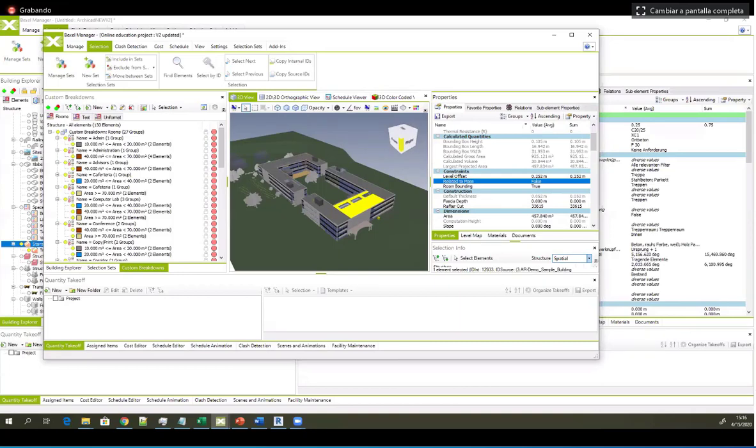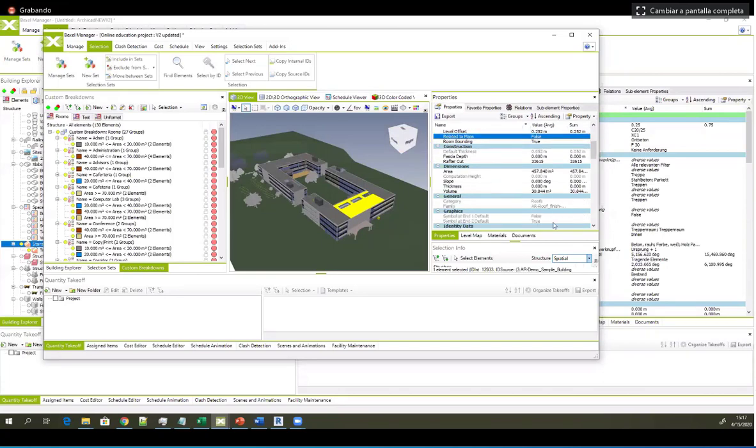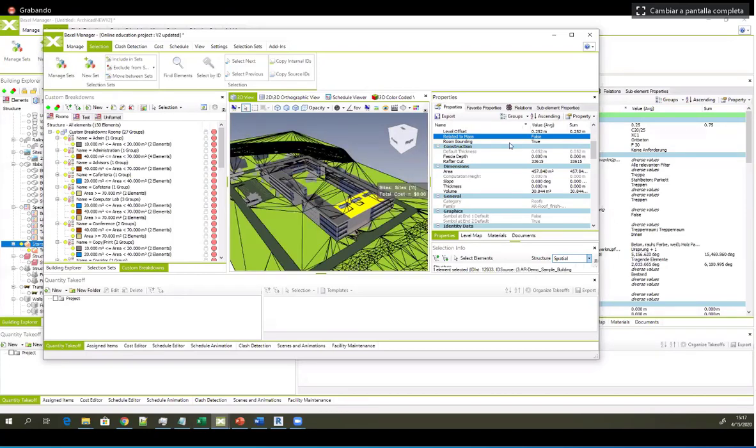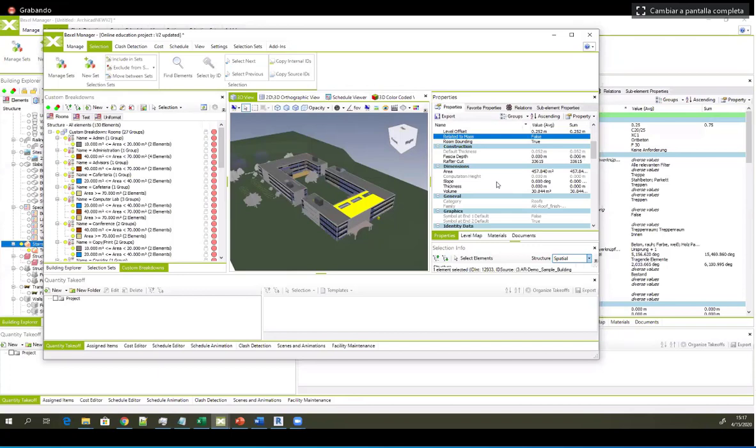Is it possible to reorganize or remap the structure of the properties group? Currently, you can only create your new groups, and the existing structure is coming from the authoring tool or from the IFC file, so it's not currently possible to reorganize it. And this is maybe not really recommended, because sometimes according to BIM execution plans, you specifically want to put a specific property into a specific group.